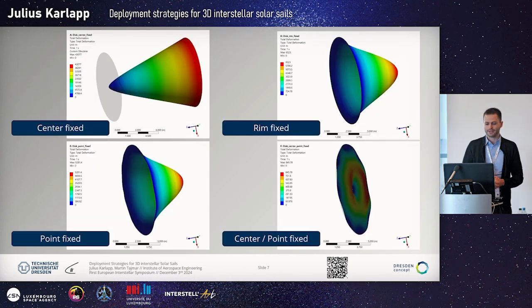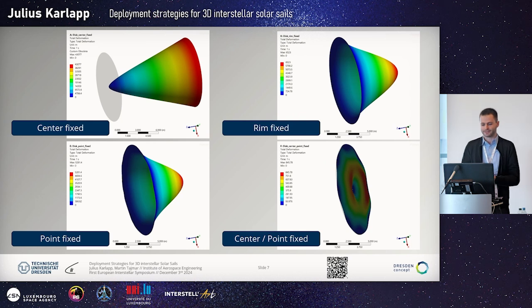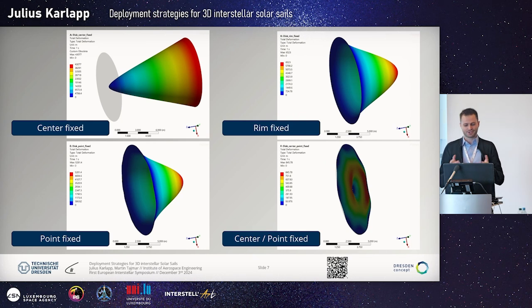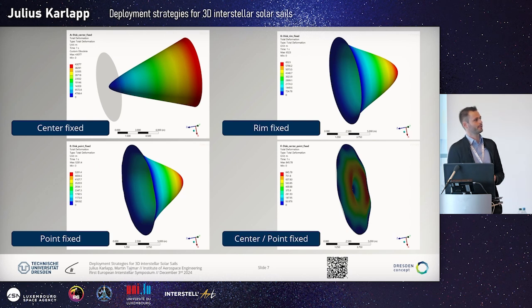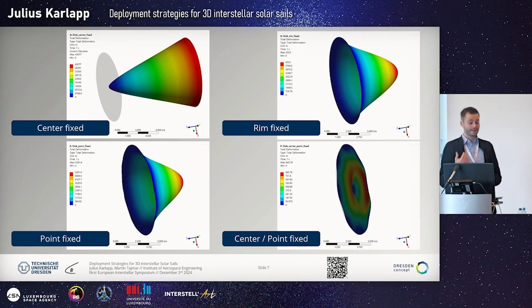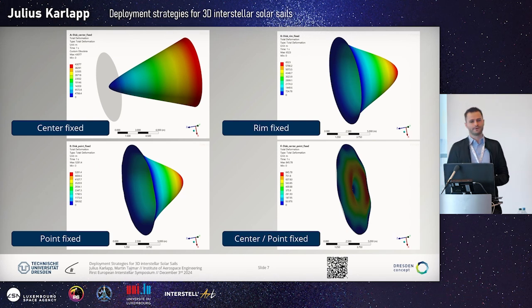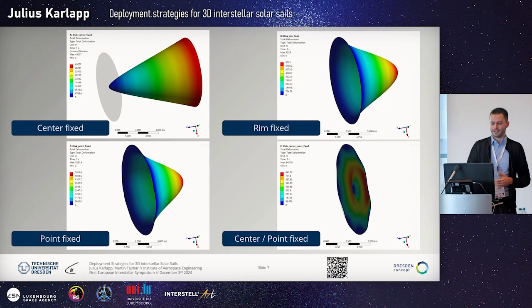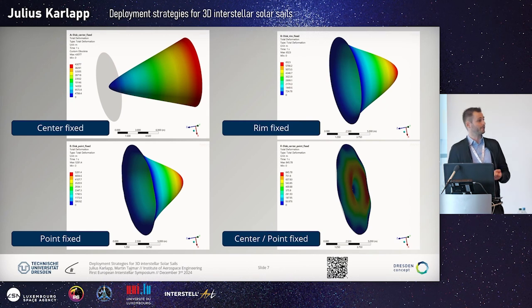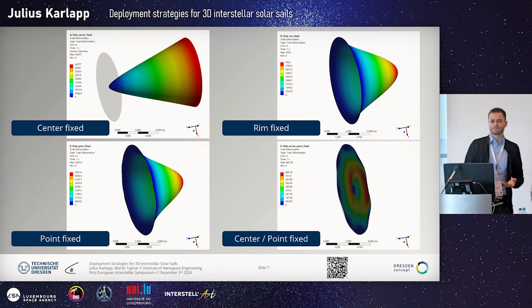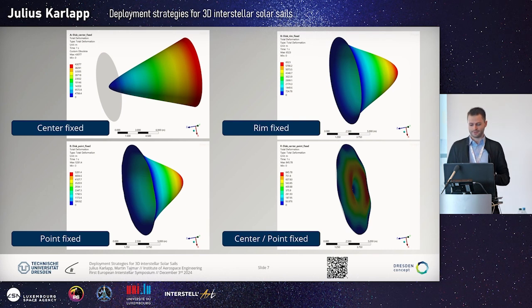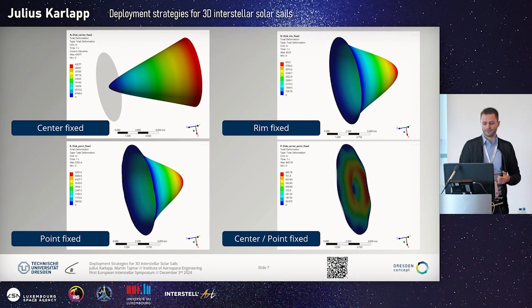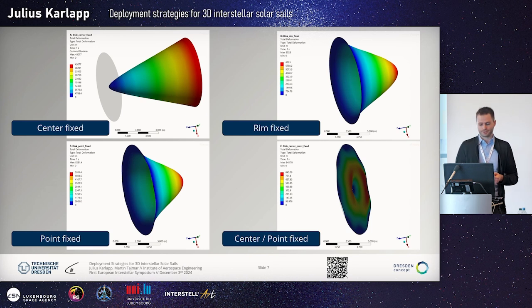First, we simulated a standard 2D unsupported disk shape of a sail with the preliminary parameters of 3 millimeters of thickness and a diameter of 10 meters. For this, we implemented a material model for the Aerographite, and this model is based on the research results of our colleagues in Hamburg, and will be further developed in the future.